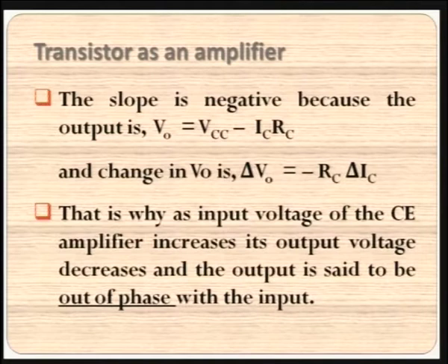In oscillations and waves, and also in optics and other topics, we come across this phase very often. Here also we will be giving a sinusoidally varying voltage as the input for an amplifier. So, the phase concept is to be learnt. There will be a phase reversal of 180 degrees happening in the case of an amplifier which is designed using a transistor in the common emitter configuration. It is found only in the common emitter configuration.